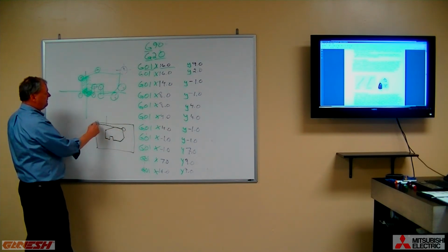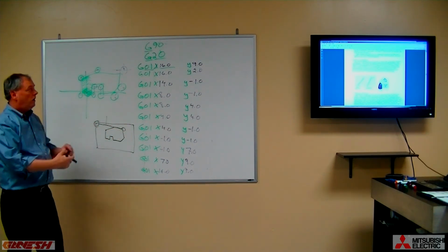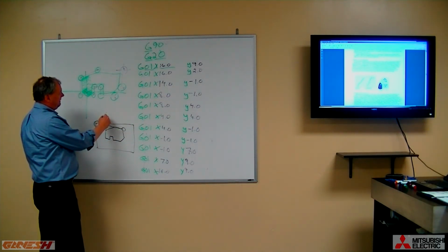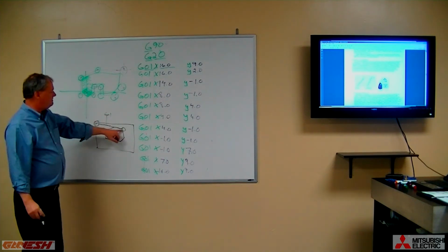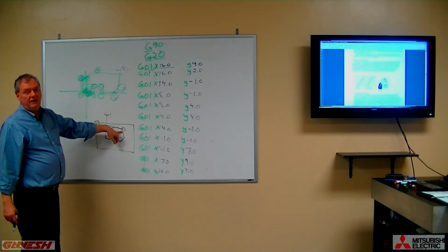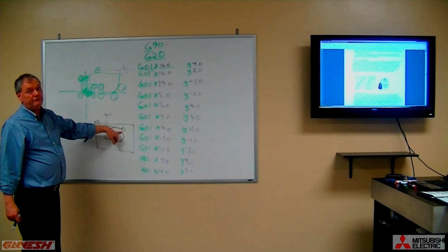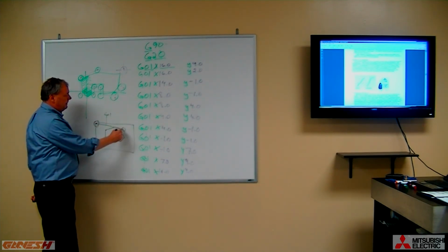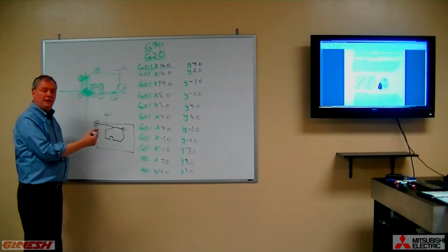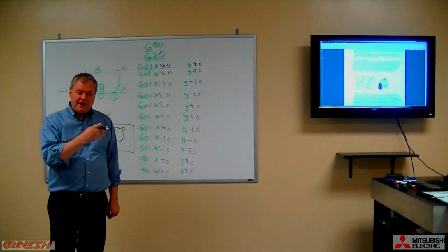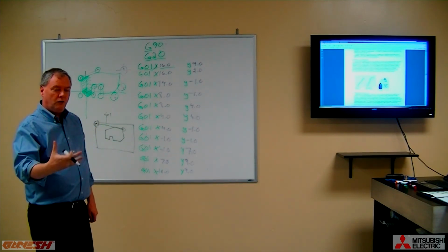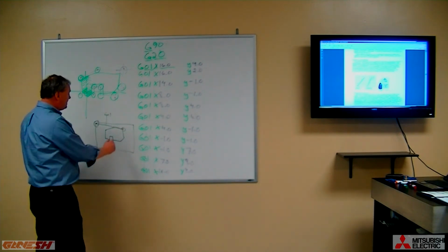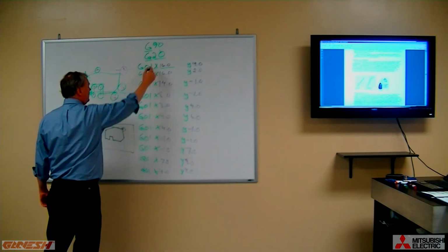This move, depending on where the tool is sitting before it starts running your program, would be at a feed rate. So if this move were 20 inches and your feed rate was set to move at 5 inches a minute, how long would it take you to get from point A to point B? It would take you 4 minutes, right? Because at 5 inches per minute times 4 minutes, you have 20 inches that you've just moved, simply to get the tool over the first cutting position.